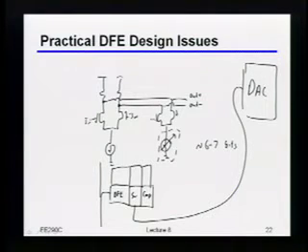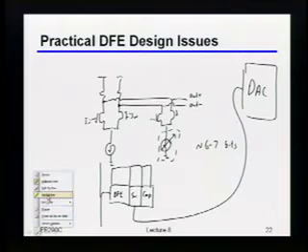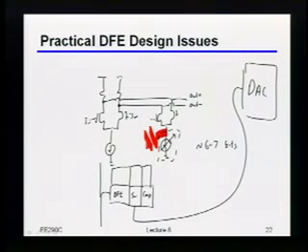The only caveat is that now you have to be really careful, because obviously there's a whole pile of capacitance on that tail node, which can cause some interesting issues. But as long as you're careful about it, this is generally how you're going to want to arrange your layouts. I think I may have mentioned this in the past. If you look at a lot of very high-speed designs, this is indeed the type of thing that they'll end up doing.